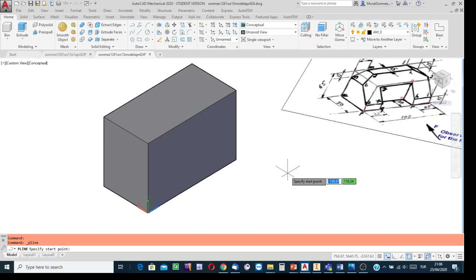It is at the place along this edge, but 15 millimeters away from the bottom side. Since the origin is just on the bottom side surface, I'll write the coordinates for the starting point to have the edge of that inclined surface.